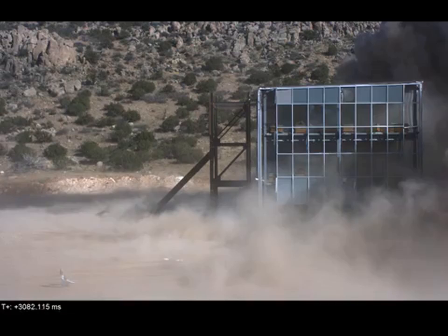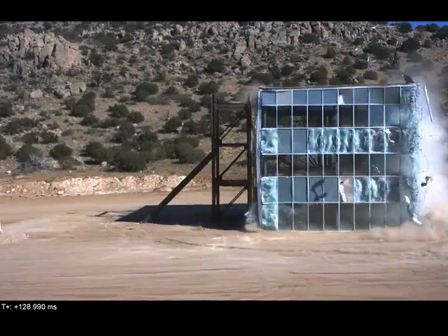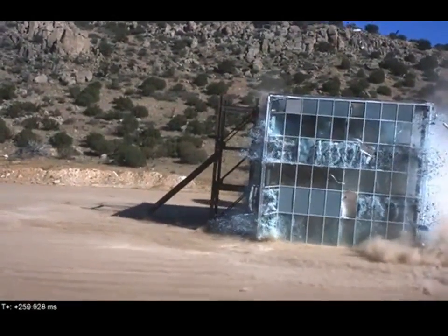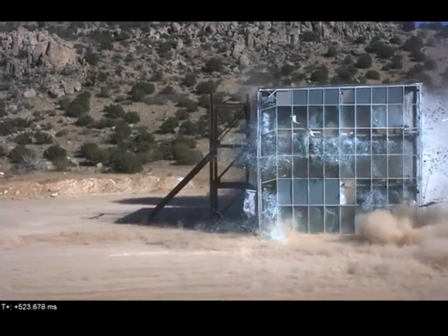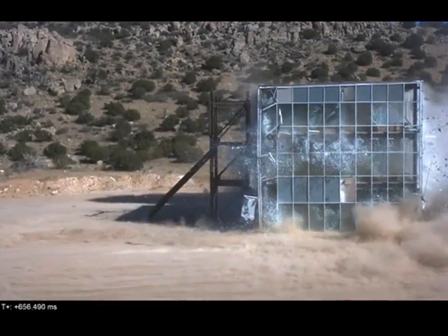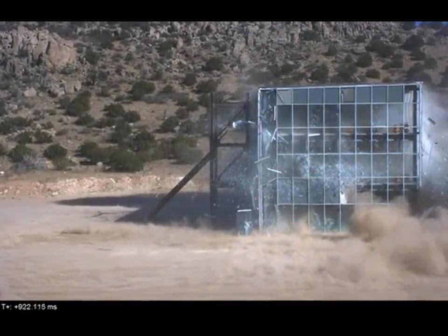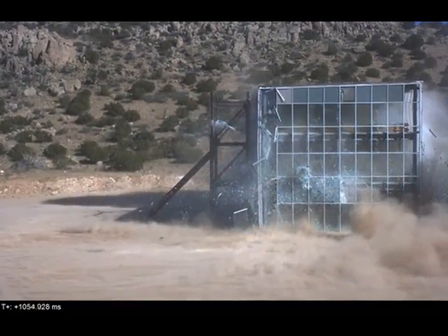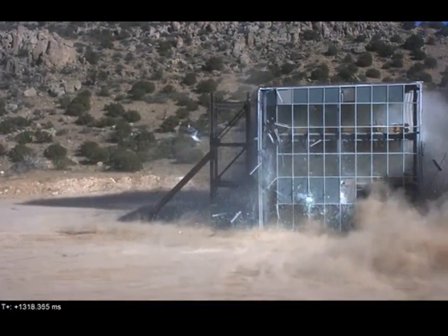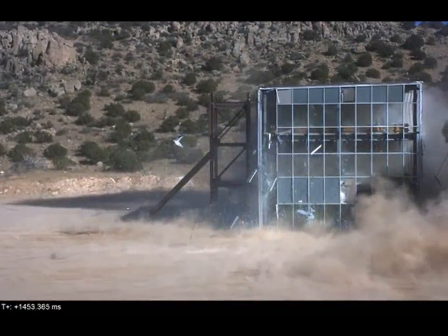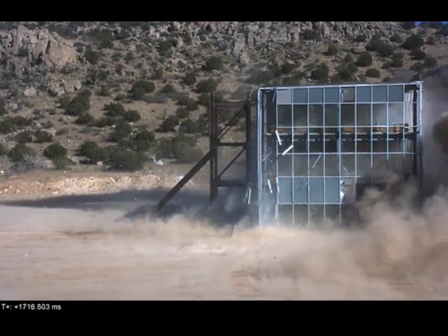And finally, I want you to pay attention as I play it one more time. The lateral response of the frame itself is minimal. We see a lot of shaking happening, and that's from the ground shock, which is a component of a blast load that Kirk mentioned. You can design for that. It typically requires the blast load to be very, very large. But in terms of the sway response of the frame itself, it's minimal, and that's generally because of the differences in load duration and the natural period of response of these buildings, and we're going to cover that later